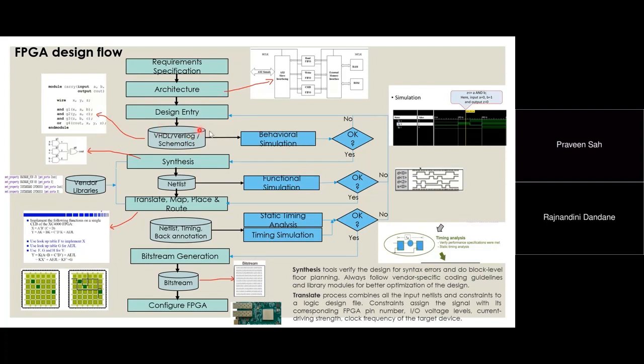So here what happened? The code whatever you have written, it is not fully compiled. You are just checking whether the RTL code you have written is working as intended, as expected or not. Here the timing information, setup, hold time, slack, is not considered during this behavior simulation.